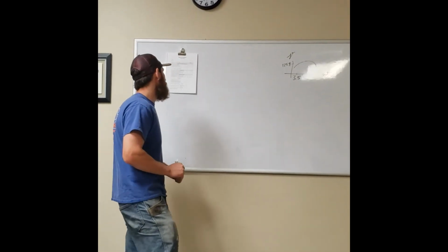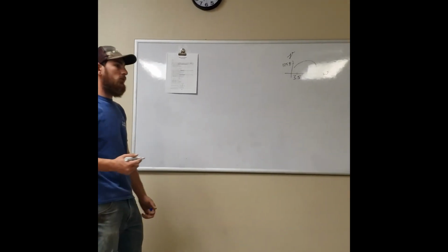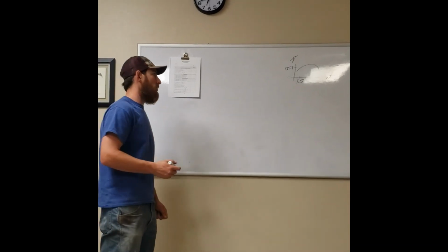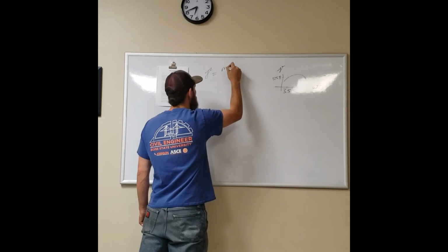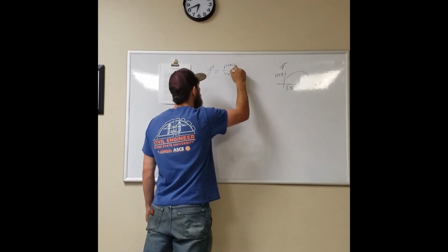Okay, so for the sand cone, the first thing that you've got to do is calibrate the sand. We've got to come up with a unit weight for the sand. Again, that unit weight is just equal to your mass over volume.